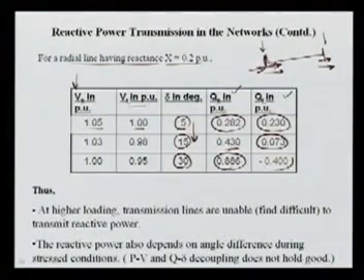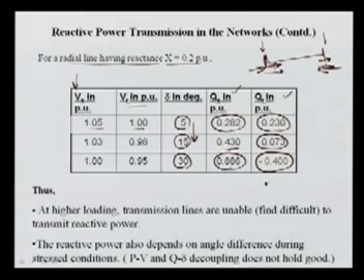we can say the reactive power generation here is almost 88 MVAR. However, on the other side it is negative. It shows that reactive power is again consumed by this line and the reactive power is flowing inside this line. Now if you see the voltage profile of this line, I can draw one axis here, this is 0, let us suppose 1 per unit here, and here Vr is 0.98 in one case. Here 0.95, let us suppose.